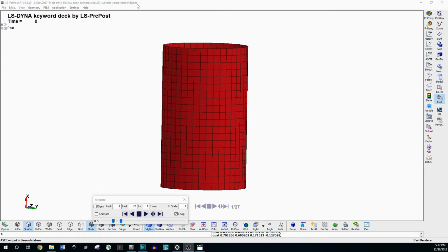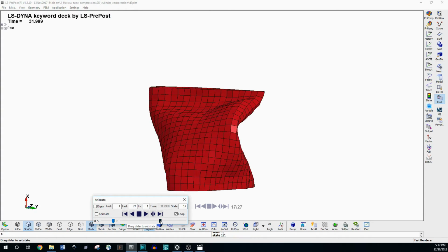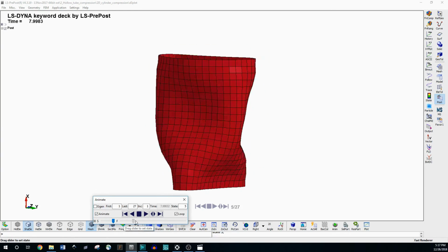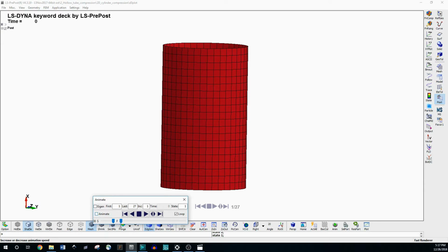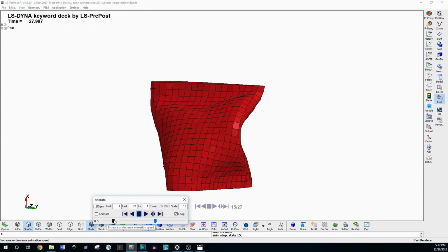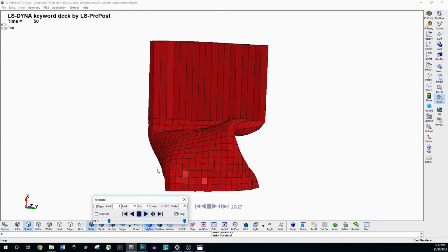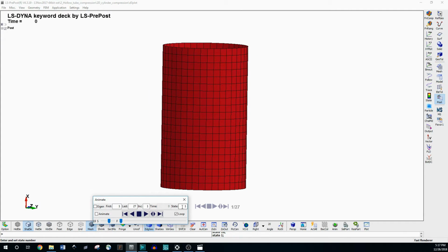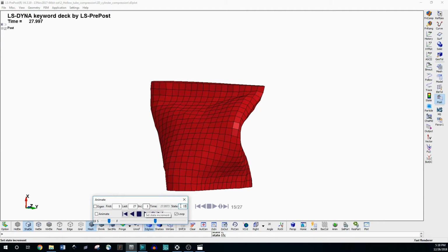If you have the D3 plots open, this is your animation toolbar, which you kind of went over. If you drag this, it'll view the last point wherever you let go. But if you click animate here and you drag, you can scroll through the frames like this. You can also hit play to actually play it, and you can change this to a number of frames per second, and it will slow down the animation. You can also search for specific states or frames here. So if you know your video's got 30 states and you want the middle one, you can type 15, hit enter, and it'll take you to state 15.